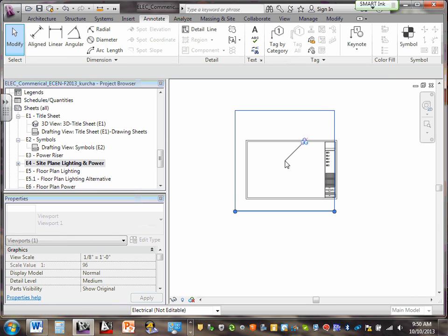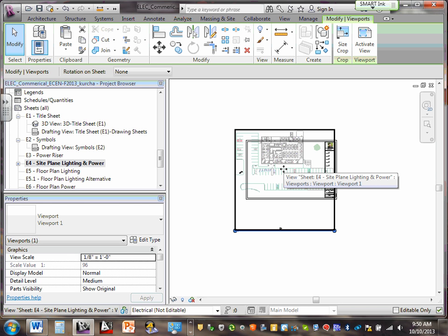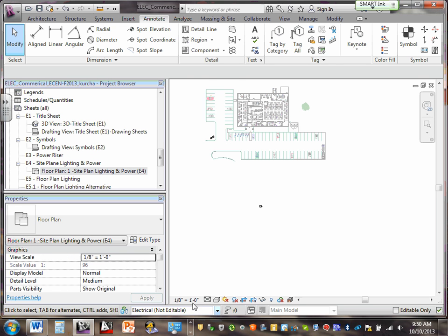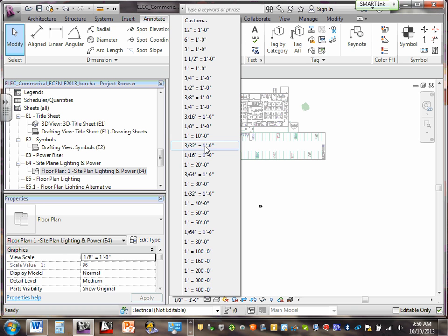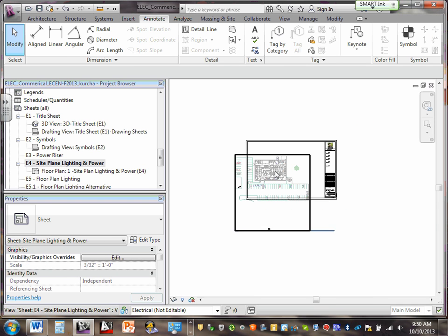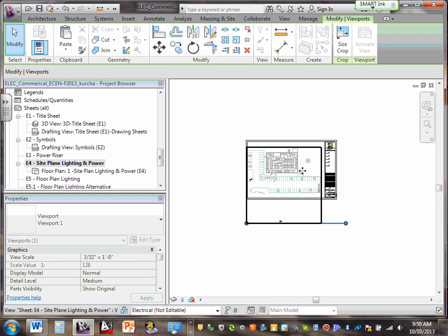And you got yourself a view. There's one little problem though. What's the scale on that baby? The scale is screwed up. So do me a favor, the scale that works is 332. Drop it. Can you guys see that? It's not fitting, right? So we're going to expand this one right underneath it, click on this, and change the scale to 332. Everybody change it to 332. Go back, double click on the drawing itself and drag that boy and put it in here. So that should fit.